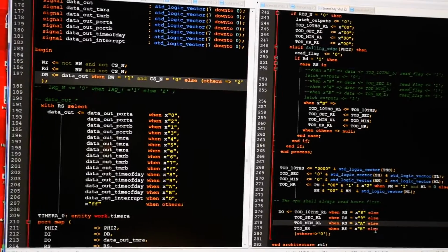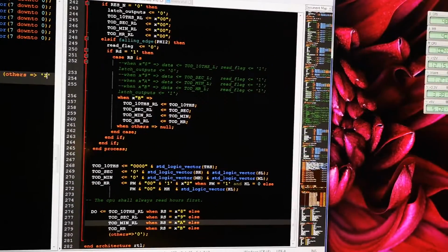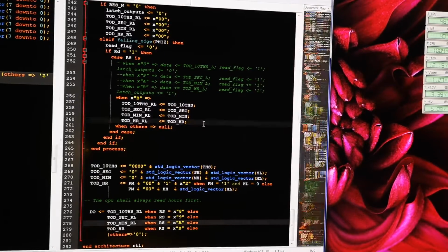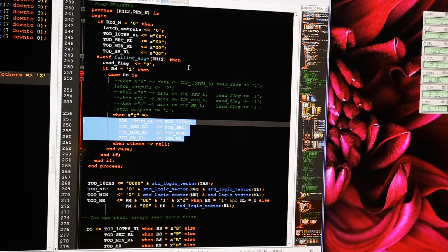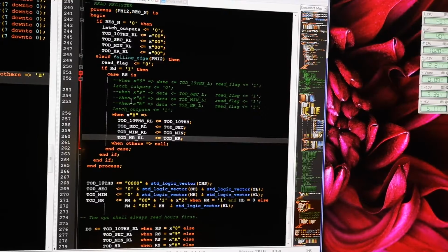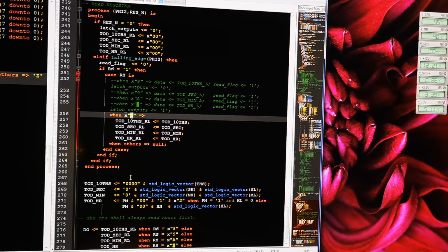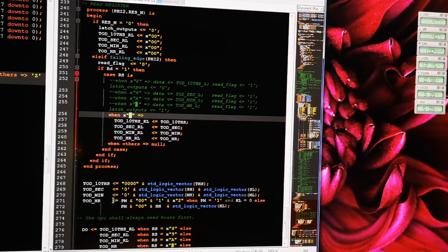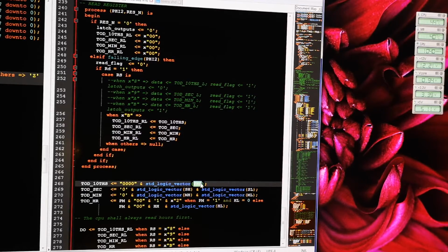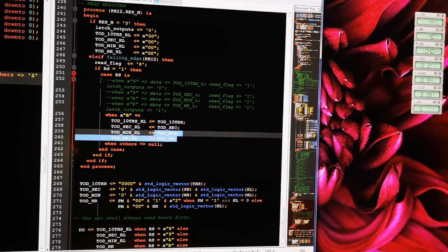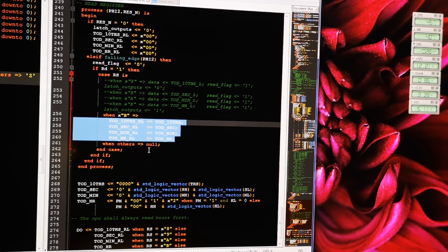Anyway, so back to the problem. Why falling edge? Why does falling edge work? Well, we want to store this whenever you have a falling edge on a read. Because first we want to read hour, and then we want to read minutes, and then seconds, and then tenth. And meanwhile we are reading those, the counter can change. So that's why we want to store all of them in a latch on the first read, such that when we read the rest, they will not change.